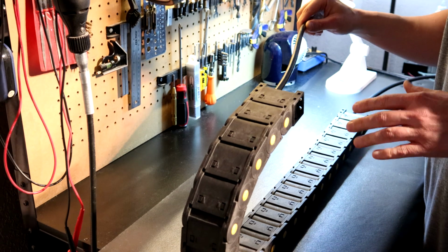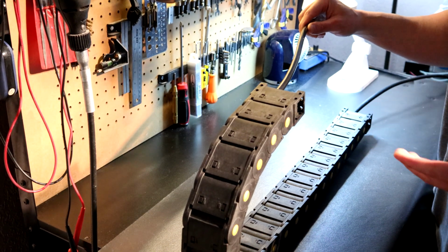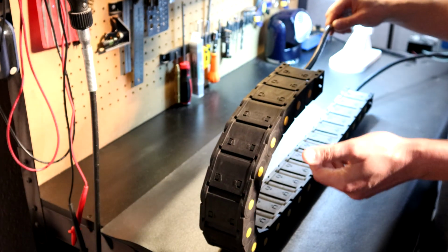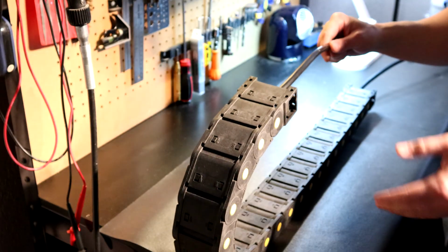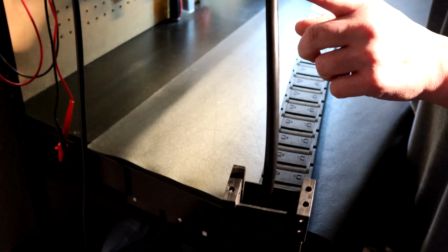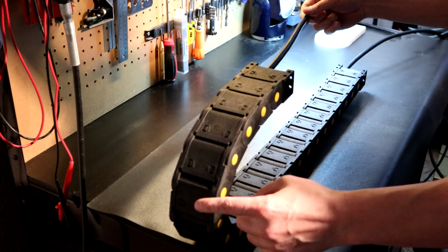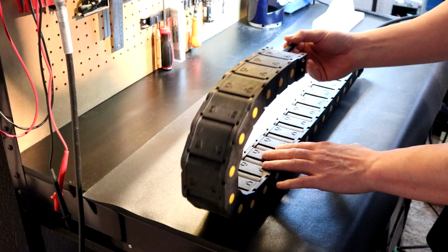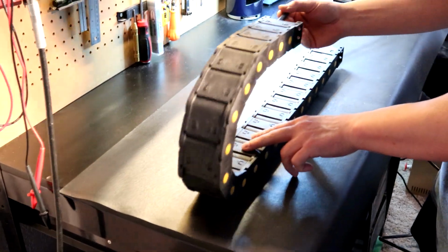Can any vendor dictate lifespan on their cables? Absolutely not. There's no way we can do that because there's no way we can dictate what you are doing with your cable chain. If you properly assemble the cable chain with the cable in it, everything is set, you're going to find the sweet spot. What I mean by the sweet spot, you can see how the chain actually wraps around. There's no stress here on this cable at all. It can move, everything is set.